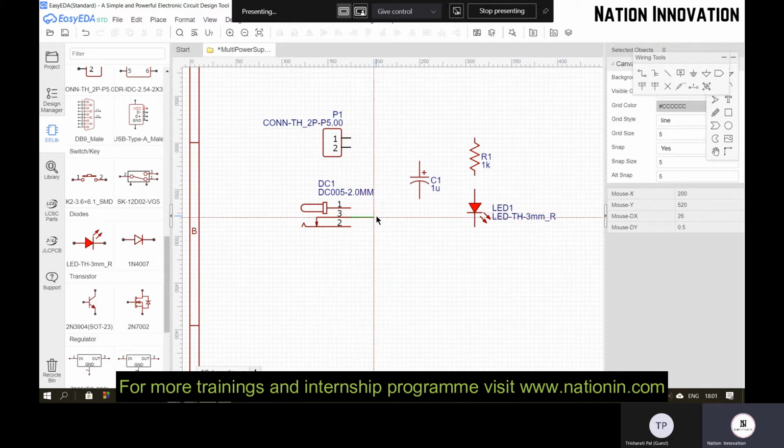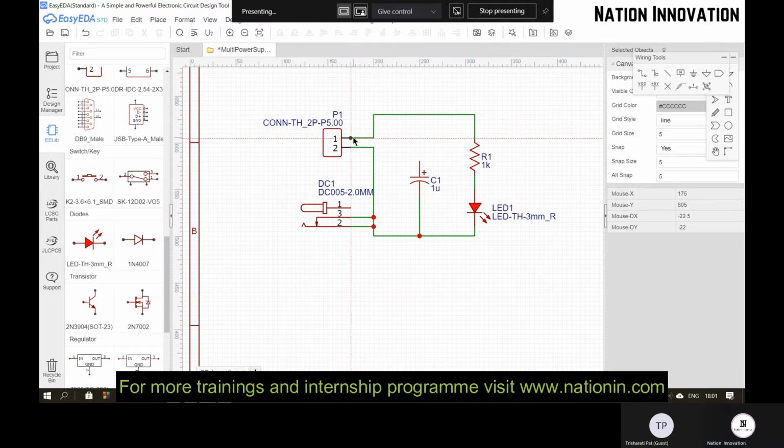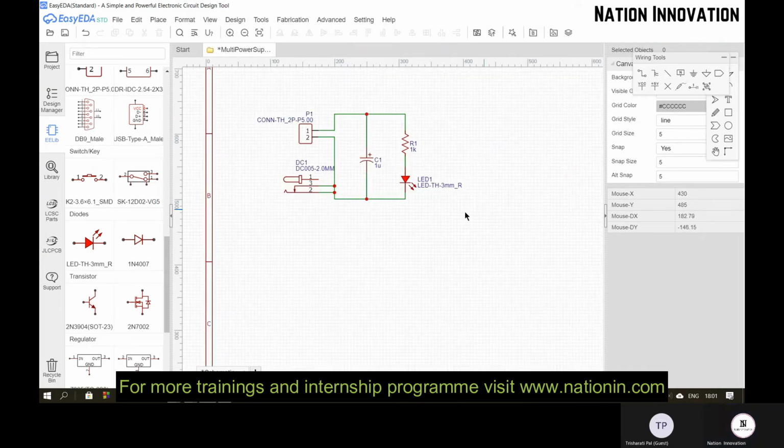That is third and second pin are shorted and connected to the ground pin. And again your second pin of the connector is connected to the ground. And same here, the cathode of this LED is connected to ground pin. So do the connections like this. So the capacitor will filter the noise, whatever noise coming from the input. And this is the DC power supply.